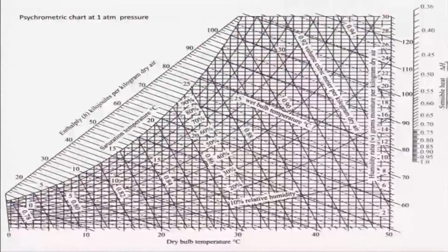As I was telling, this line, which earlier was a green line, is basically the specific volume per kg of dry air, the water vapor volume per dry air. And this dashed line, if you look at it, gives the wet bulb temperatures. Like in this case it is 25, in this case 30, and then it goes 20 and like that, 15, 10, 5, 0.